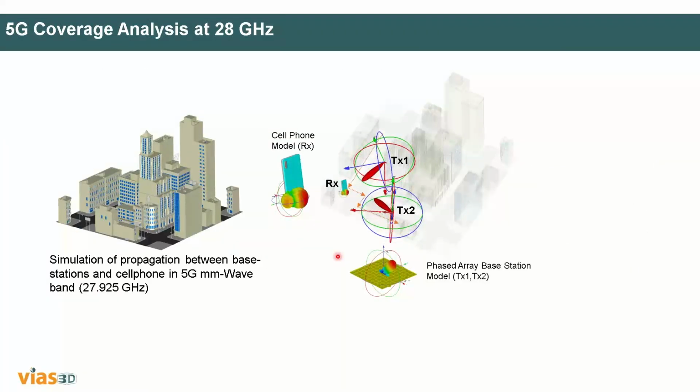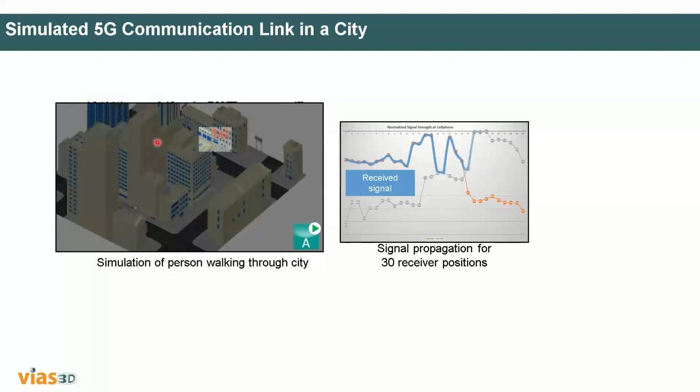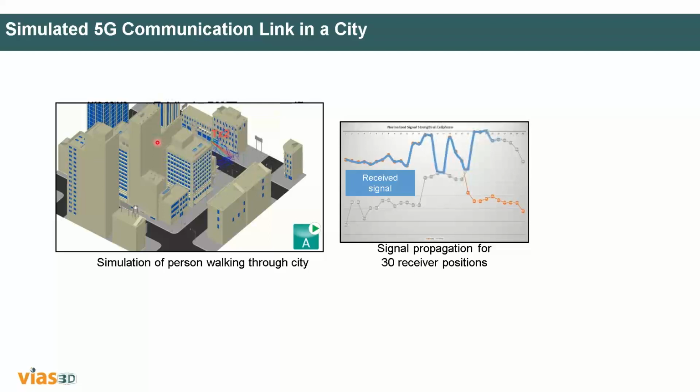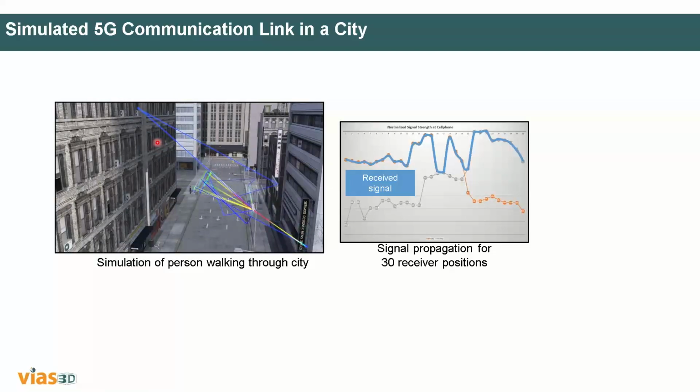Another thing is you can do propagation model analysis, especially 5G coverage analysis. Just like you can see here, you can have this kind of building. You can place your antenna at one point, and you can try to move that antenna. You can see what kind of interference is actually happening at the receiver. So basically, you know that these studies are nothing but propagation analysis, where you are understanding the multipath reflections, in terms of noise and loss conditions, like Rician fading and Rayleigh fading.